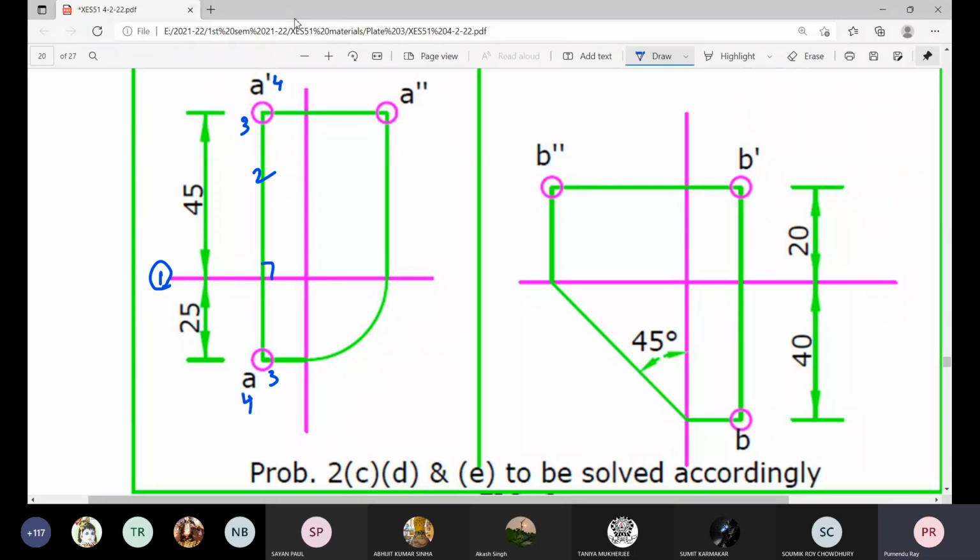In the next step, we identify this plane and elevation A and A dash. In next step, step 5, we show these extension lines, the dimension lines, the dimension arrowheads, and these dimension figures all in step 5. Step 6, draw this axis. Step 7, through this point, draw a line parallel to GL.